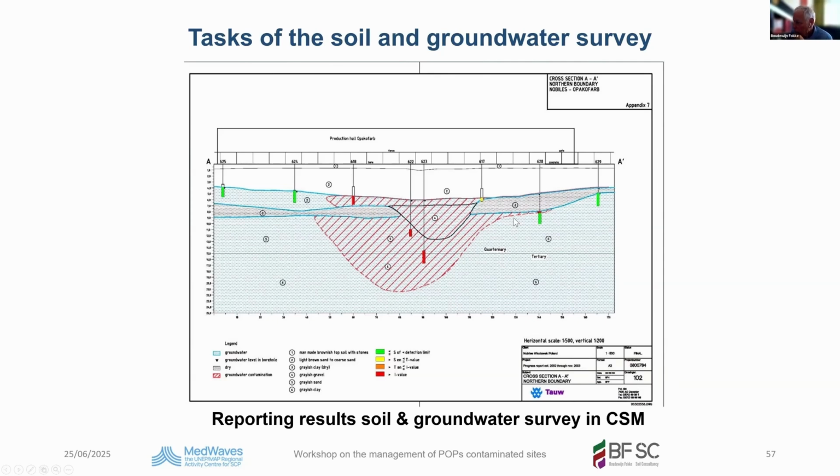and we found out because here this borehole 628 was taken, and then we say, hey, it's clean, but we continue through this layer, and then we saw that at the bottom of this layer were some traces of contaminants, and that made us proceed drilling, and then we found out that this layer was intercepted and that under the aquitard was a plume. So in this case, this cross-section illustrates the situation. This was in Poland and the result of contamination by a paint factory.